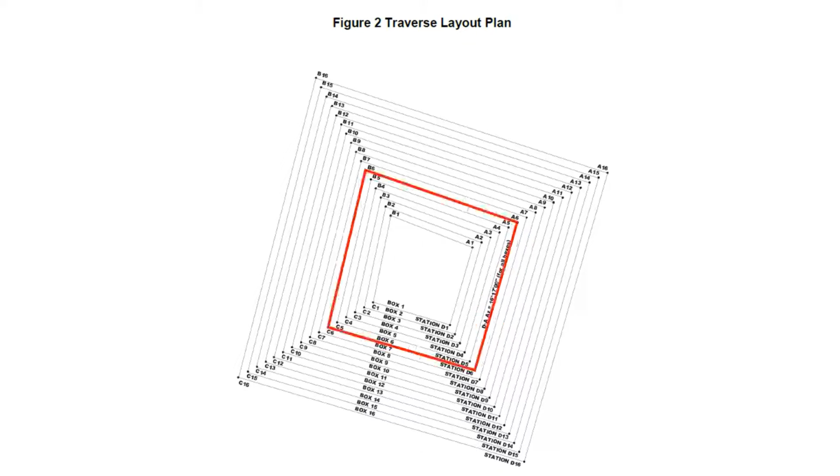We're going to pick one of the boxes that we can see here and complete a survey for each of the 4 corner stations. The process of today's lab is that we're going to set up a total station over each of the 4 corners and measure the interior angles and horizontal distances between each of those 4 stations.